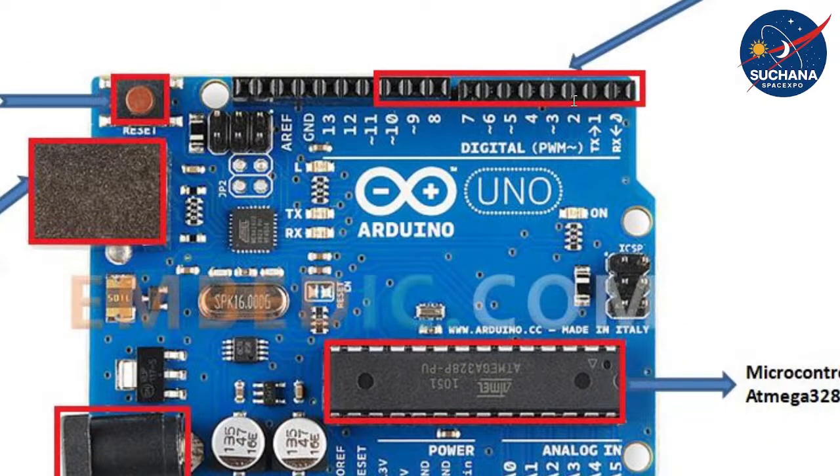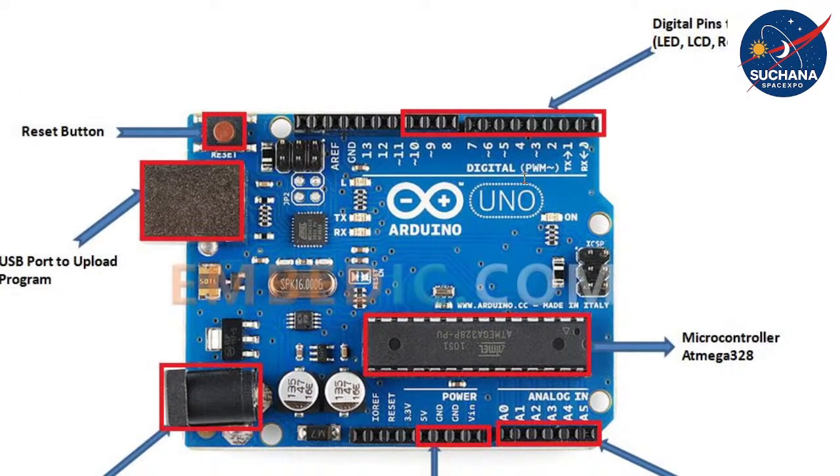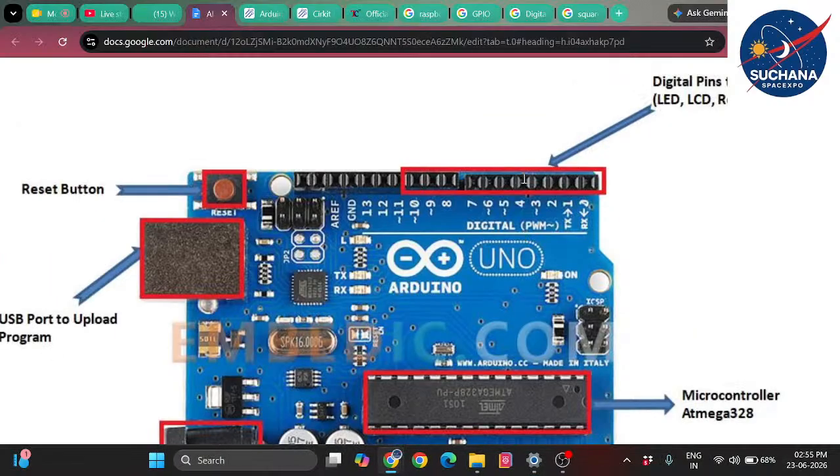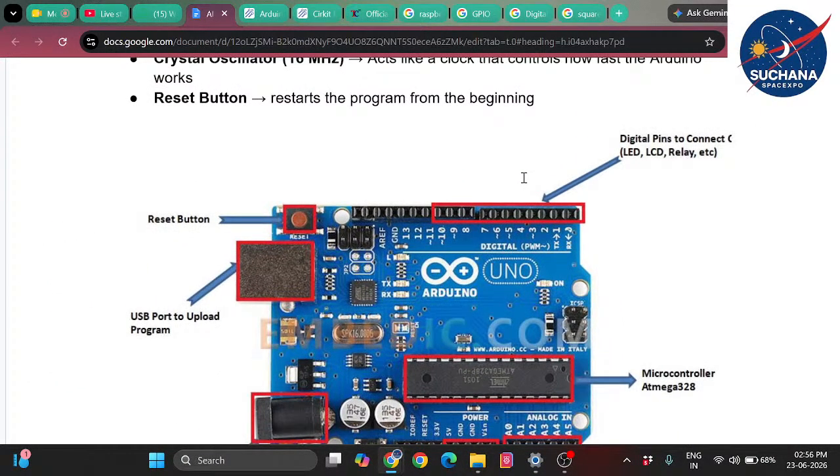And also one more thing, the 0 pin, we call it the RX pin. Another name for 0 pin is RX pin. And another name for digital IO pin, GPIO number 1, is TX. Okay. So it is already clearly labeled in the Arduino module itself. 0 means RX and 1 means TX. TX means transmission, RX means reception, receiving. So this is about digital IO pins. In the upcoming session, we will be exploring this in detail.